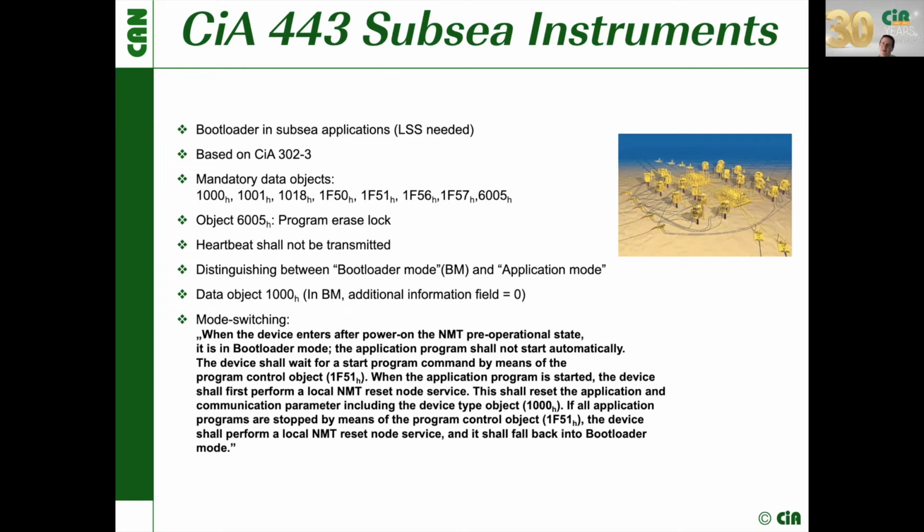And furthermore, when the other ones said, we need a heartbeat, we need a fixed node ID, here we have the situation: keep the implementation of the bootloader small. We don't want to see a heartbeat. We don't want to have a fixed node ID, but, depending on the application use case, we assign a right node ID via LSS. So I have to support the LSS service.